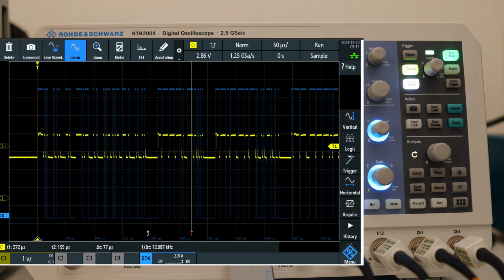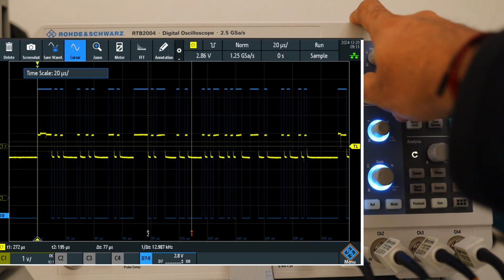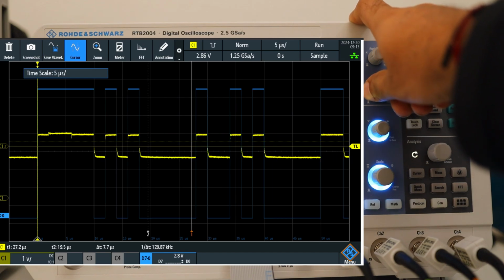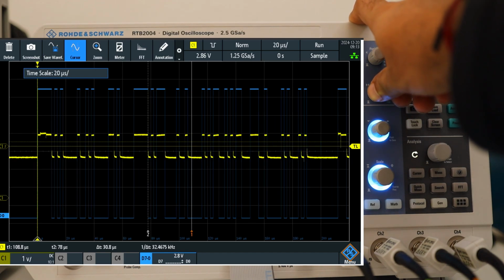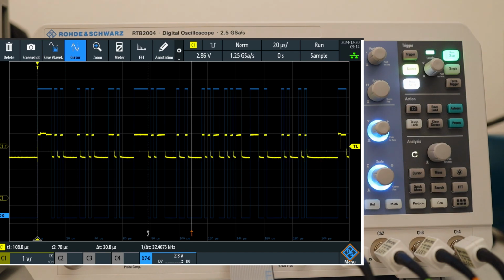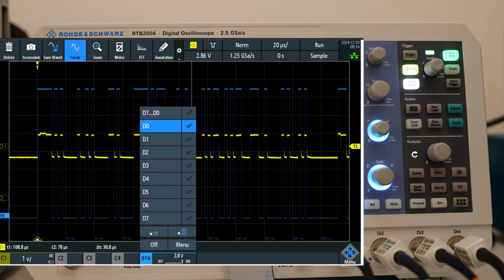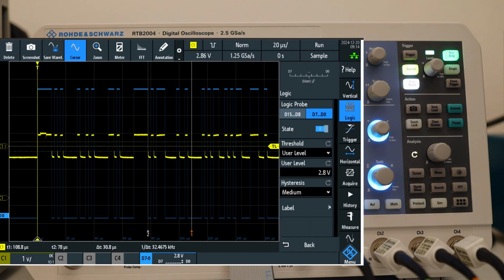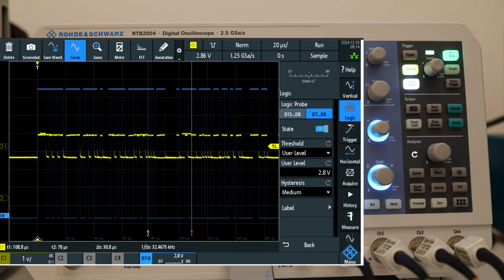So this is how the digital signal looks, and you will see it's an exact 1-to-1 copy of the analog signal. Of course, because it's capturing the right thing with the right reference. You just need to take care when you're using a logic analyzer that your reference voltage or your level is set correctly, and then the logic analyzer will also work. I'll disable it.